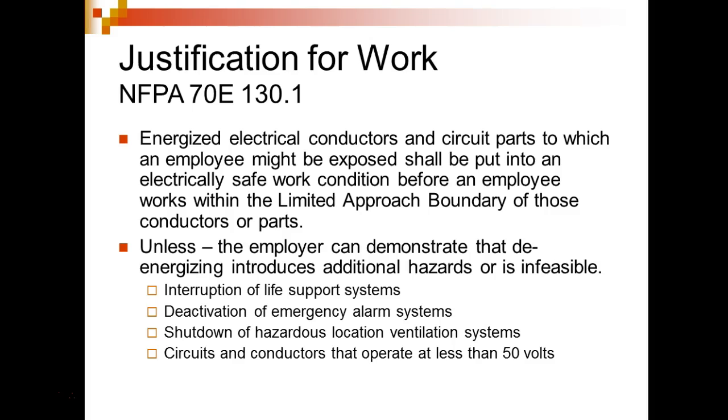Other exceptions: interrupting life support, deactivating an emergency alarm system, shutting down a hazardous location ventilation system, like in the first Ghostbusters, where the guy killed the power to the containment unit. That would be a condition where you could do that. Another: a circuit and conductor that operates at less than 50 volts.